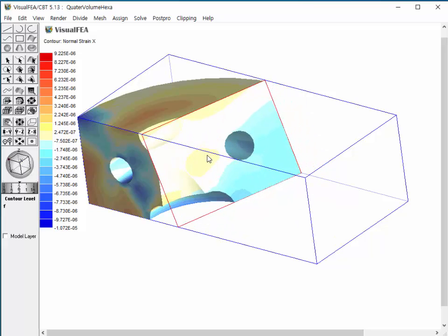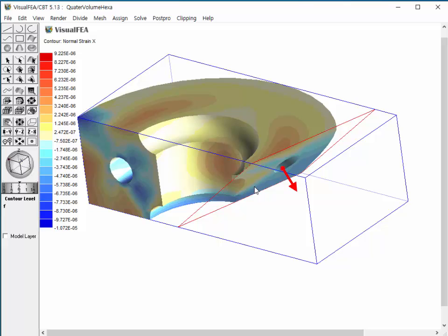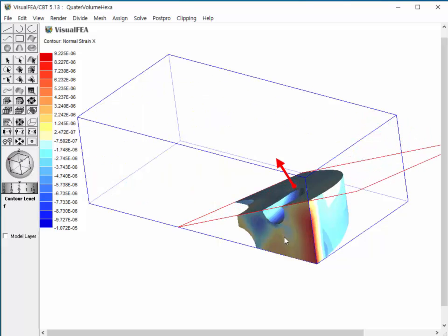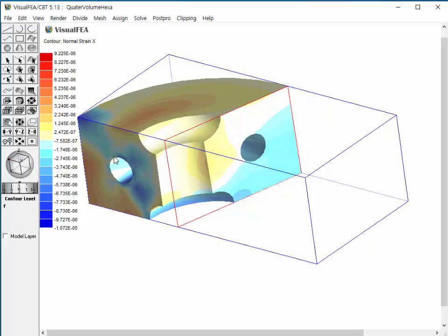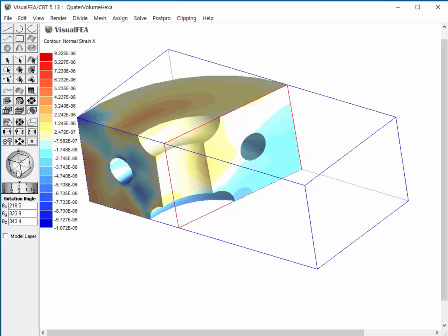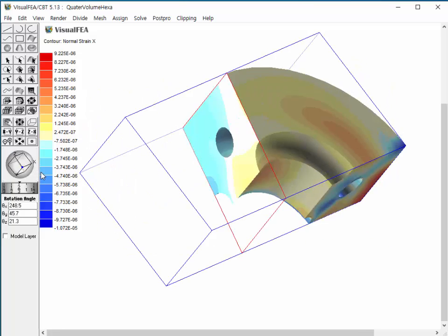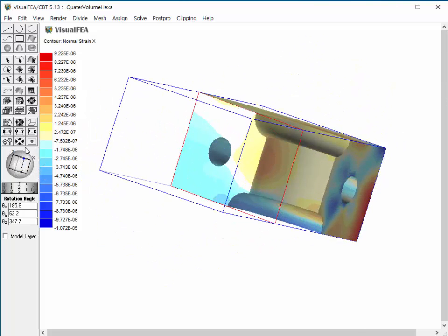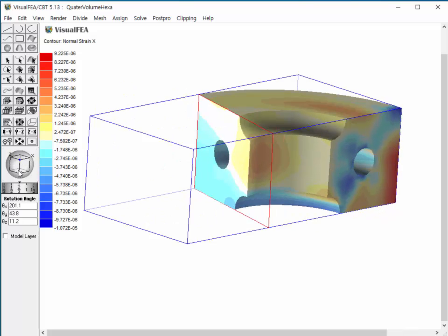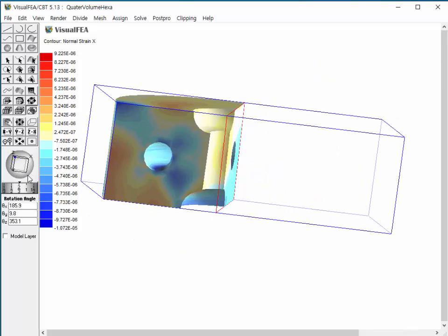It should be noted that the clipping plane always faces frontward, in the contour image. So, the displayed part of the model is switched, so that the clipping plane may face frontward. The clipping plane is kept facing frontward while the model view is being rotated. So, we can always observe the contour image on the clipping plane.